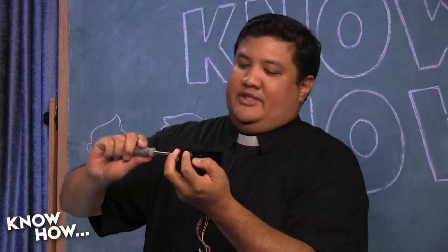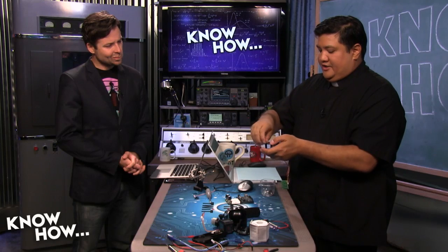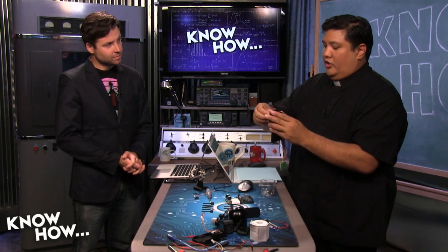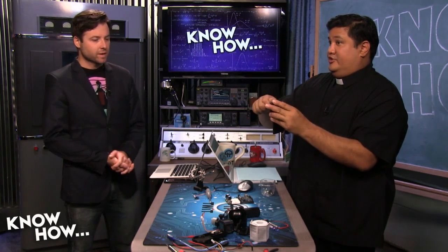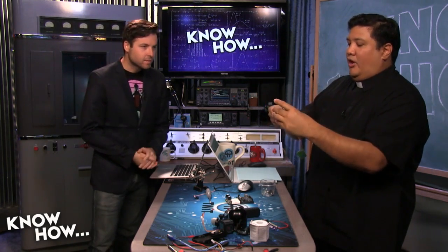It also means that the bolts won't vibrate free, because stepper motors do tend to create a lot of vibration, and if you haven't locked down your nuts, they'll just come right off. I'm just going to do one, but this has been designed to take longer screws in all 4 of these, to really secure it down. But one will hold it for now.